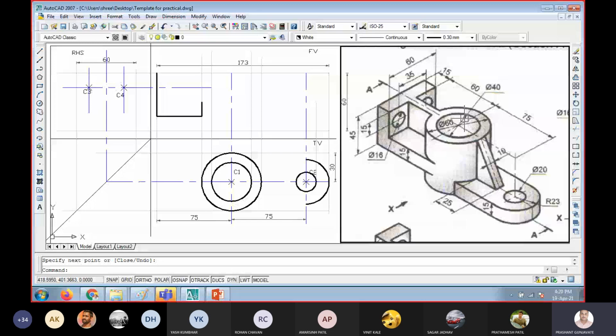Okay, then from the upper right corner I will go right side for 15 mm. Then in downward direction again, 45 minus 15, the remaining is 30. Okay, so this will be like this. Then because this part has been cut by the section plane, there are two vertical strips like this, as in the previous example. And there is a continuous line joining these two parts like in the previous example.